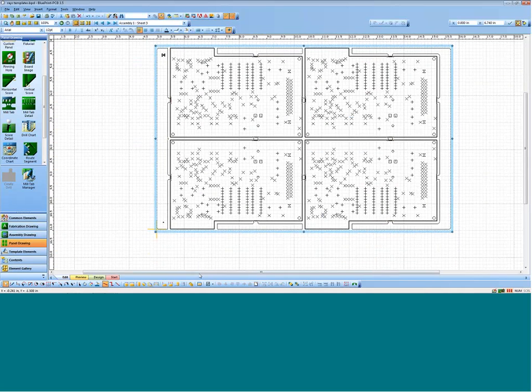Yeah, I'm going to go back and dimension it. We saw how to do dimensioning before. I can take and drop down my datum point here and snap to something. Board edge, fiducial, edge of the panel, whatever I want to snap to. And then just start dragging dimensions, dropping dimensions, and I can dimension, you know, the edge of a mill tab. I can dimension to the center of it. All of those things are available to me. Of course, you remember we had the dog legging, so I can kind of press that up as well.